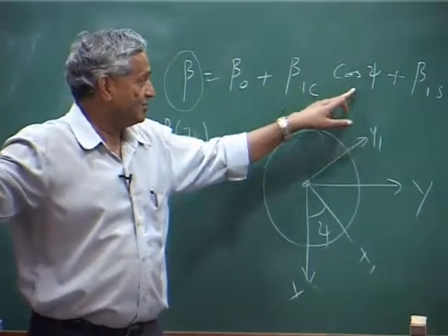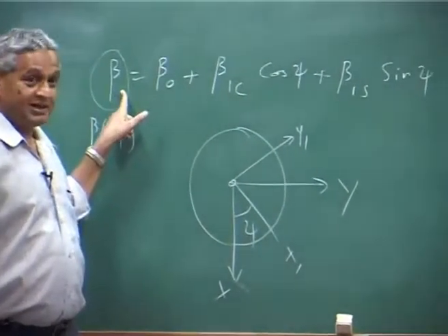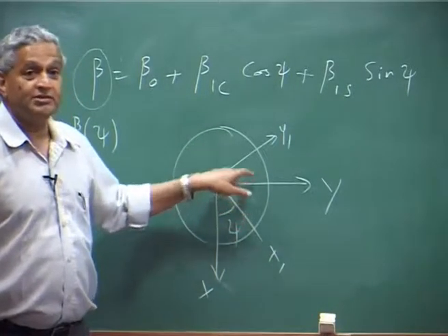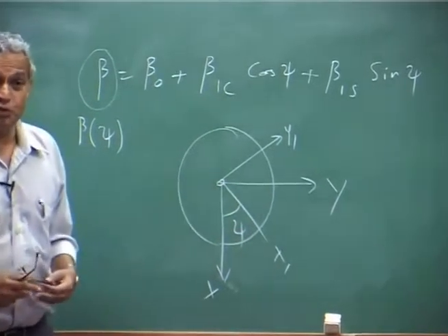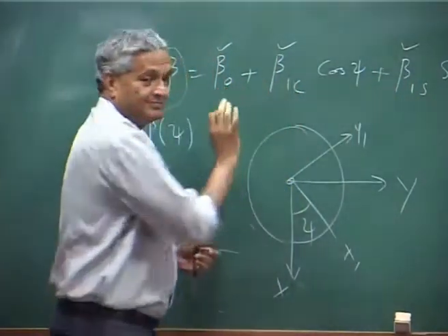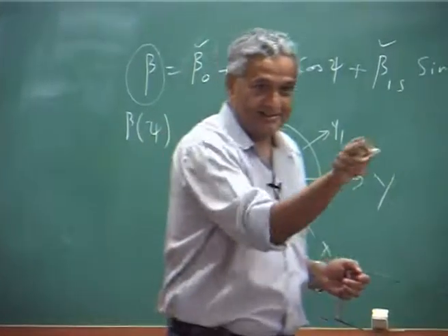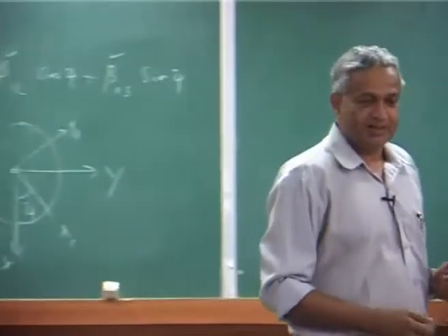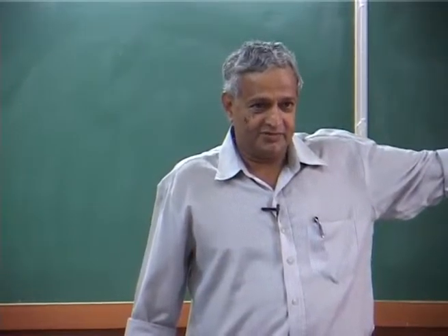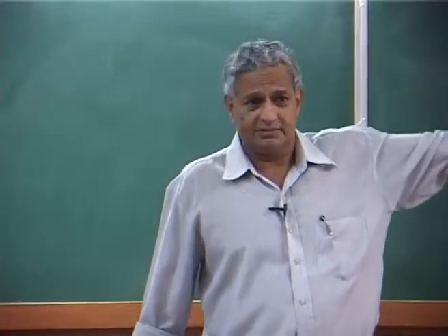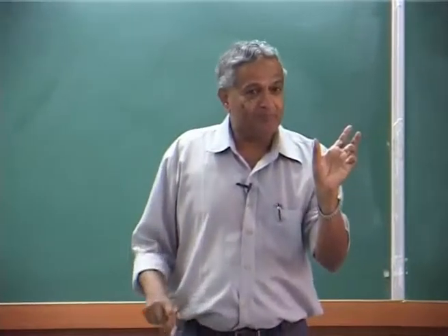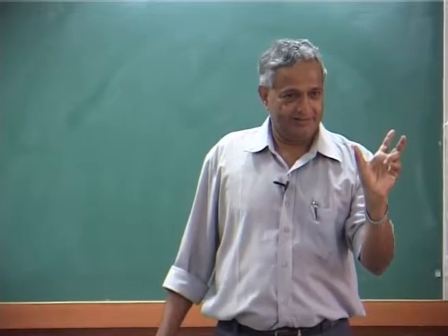plus the value depends on beta, depends on where the location is, but we do not know these quantities, we do not know what they are. That is what that equation is, because that depends on what is the aerodynamic load that acts on the blade, that force and r cross, that moment you took. That is how you get the flap equation, right.